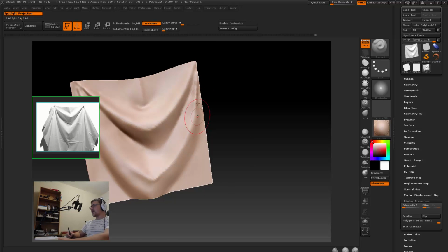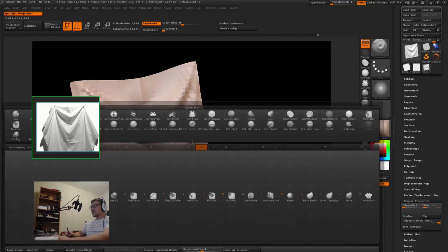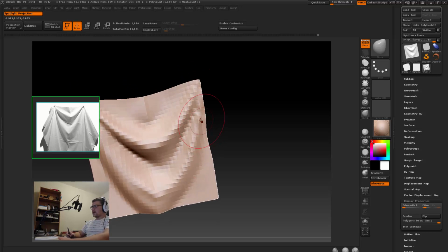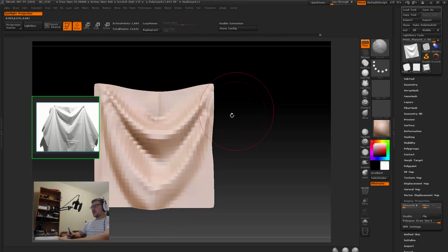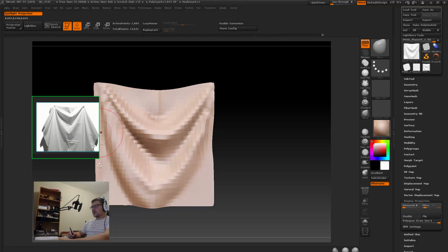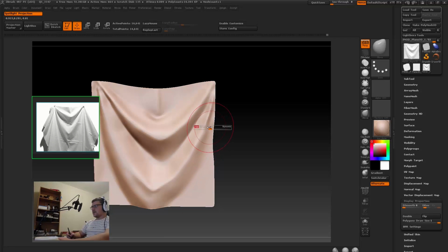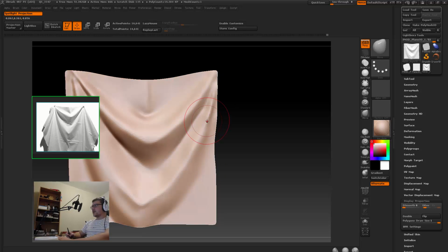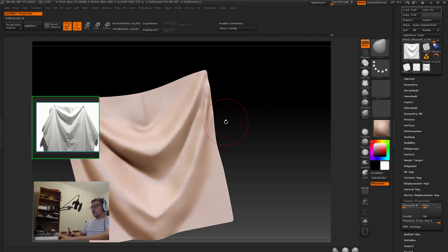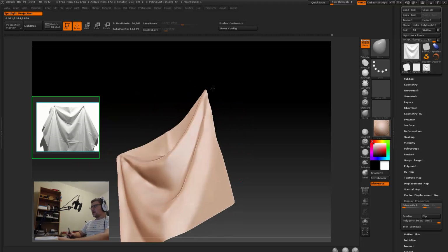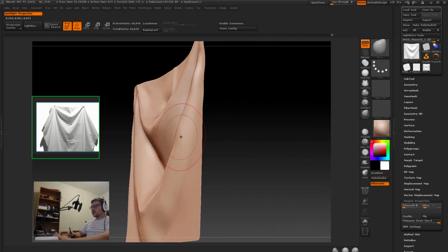At the top, I feel like this is going too much of a curve, so I'm going to go to a lower subdivision, back to my move brush. I would then just nudge these polygons around. Quite a large broad brush. It feels like these need to go a little bit more at an angle, so I'm just trying to enhance that as well. And then D, just to go back up your subdivisions. And then ZBrush tries to maintain that and make the rest of the polygons on the higher subdivisions repeat and follow that angle. Right. So I'm going to hit Control D one more time. Control D. So now we can really go and finesse certain details.